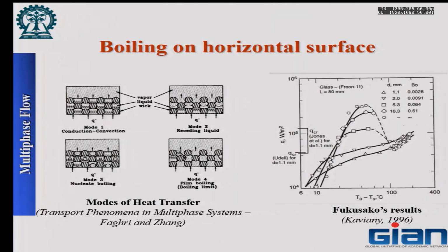If you think about boiling in porous medium, the 4 pictures on the left: at the beginning, it is conduction, it is completely filled with the liquid, and then as you start heating the surface, you have these modes. So, now let us focus on here, right. What Fukusako found was, he was doing it in a packed bed of glass beads I believe, yeah. This is glass beads and he used Freon 11, refrigerant 11.